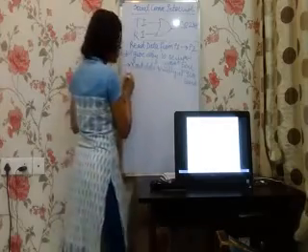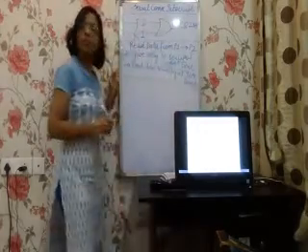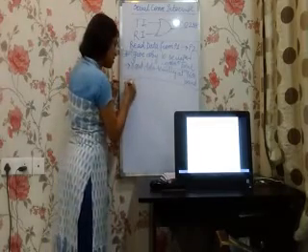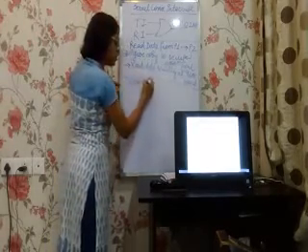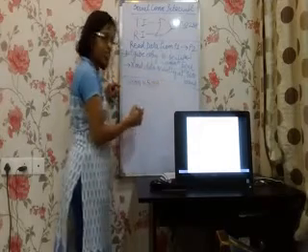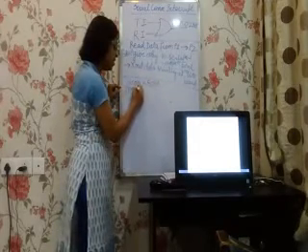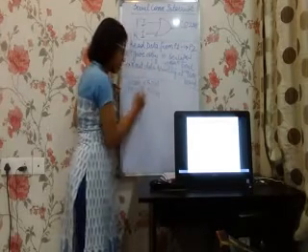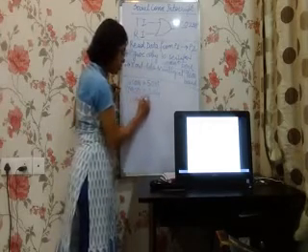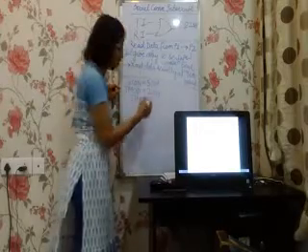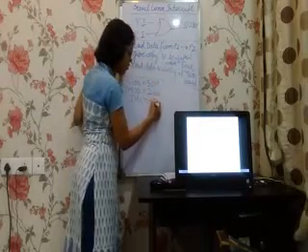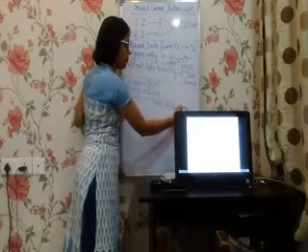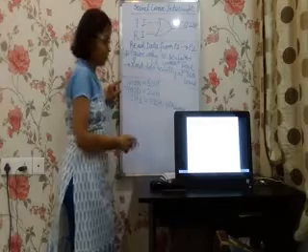The assembly language program. Before we write the program, we have to configure different registers. For serial communication, the SCON register will be loaded with the value 50H. The TMOD register, timer 1, mode 2, is 20H. The TH1 register will be loaded with a value corresponding to baud rate 9600. The value is FDH for 9600 baud, so we will load TH1 with FDH.